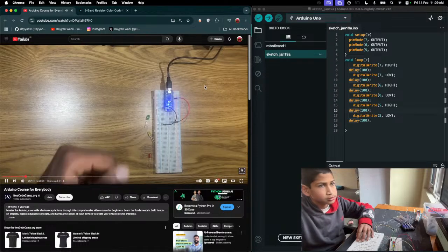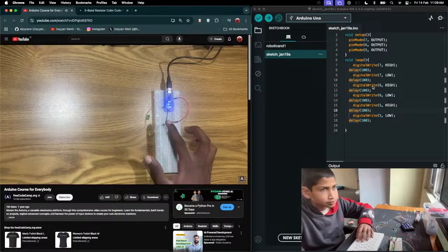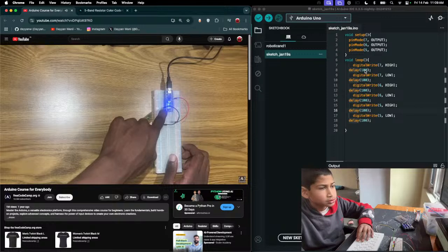Okay, so I want you to create a working traffic light. You're going to be using 3 pins, using a resistor right here, then obviously lighting up your LED, then going back to GND. Okay, so they're going to be using the same GND.